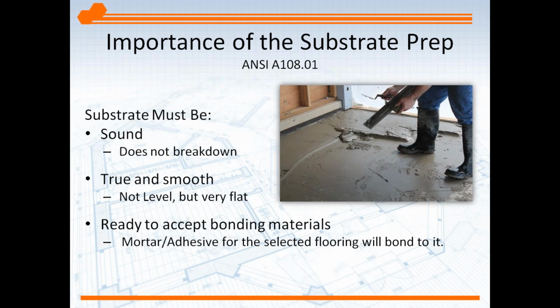Too high of a porosity level will make the moisture, the water in the mortar, be pulled out of the mortar into the concrete and change the bond strength of that mortar. So not too high of a porosity, but certainly we need porosity in the concrete.